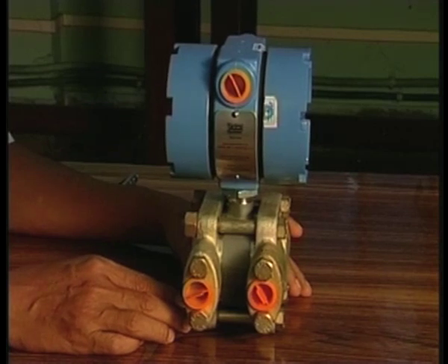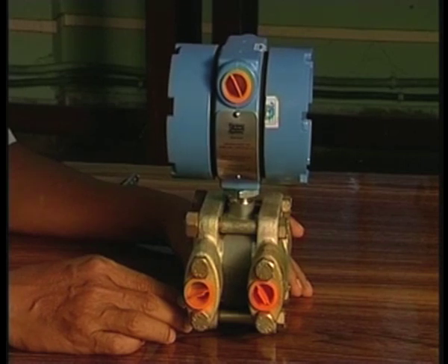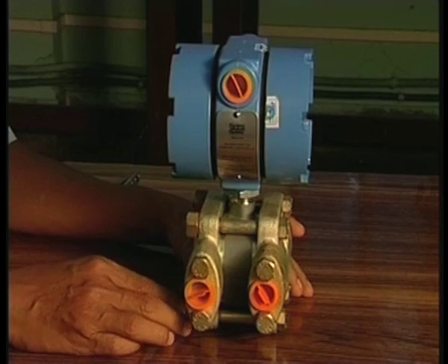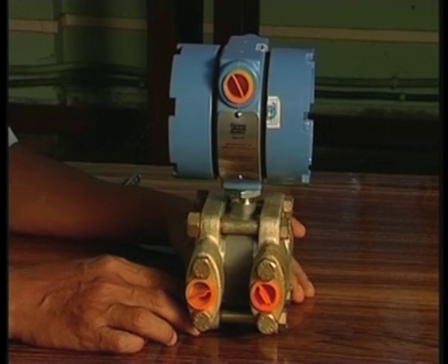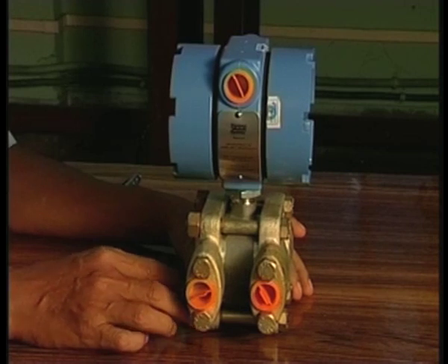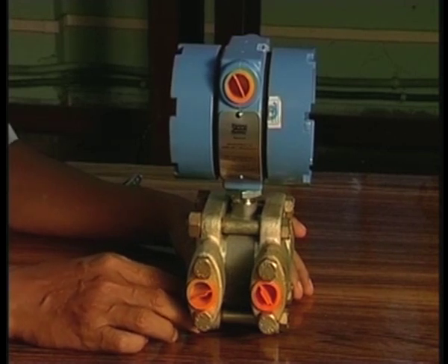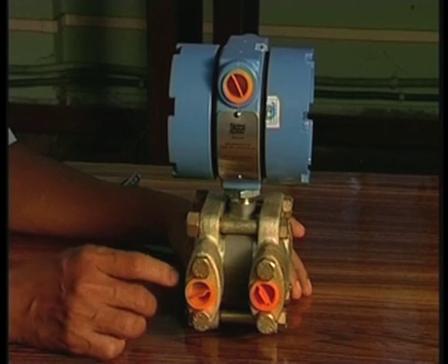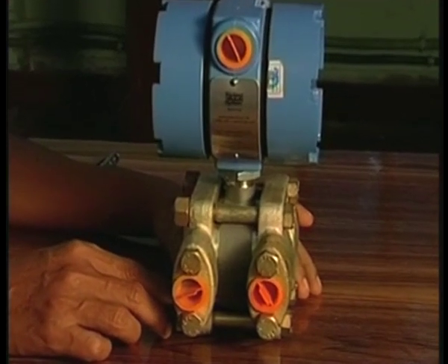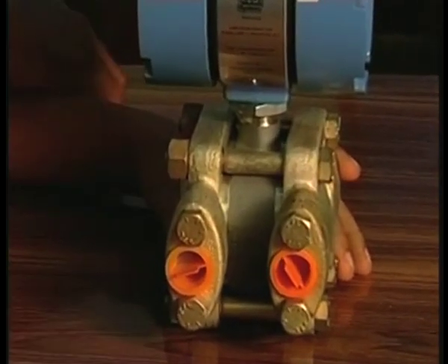We have seen in the class a manometer by which I am measuring the pressure. But unfortunately in an actual process, I need some instrument which will give a signal that can be transmitted to the control room. For that reason we need an electrical output. So in this differential pressure transmitter, there are two pressure taps, one upstream and another downstream.